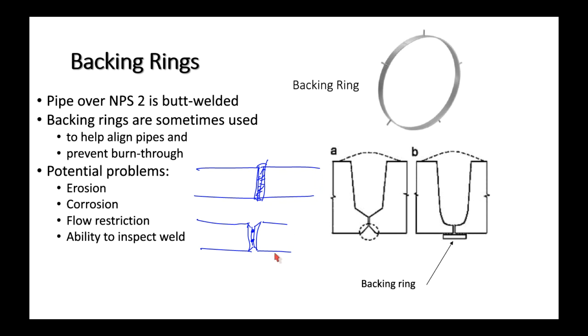The reason for the tack welds is to hold the assembly in place while I complete my weld. Once I finish the tack welds, I call over the weld inspector and say, hey, examine my tacks. The inspector is going to look for penetration into the weld surfaces, but is also going to look for cracks. You cannot have a crack in a tack, because then that crack becomes part of the weld, and that's no good.